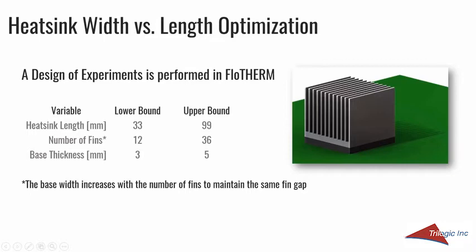What I'm varying in this design of experiments is heatsink length, 33 millimeters to 99, so it's allowed to go 3x. The heatsink will always stay centered on the component.